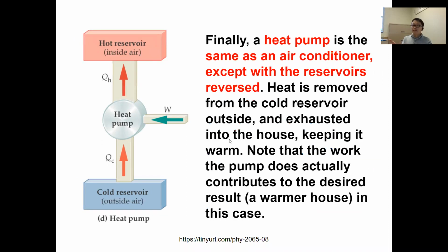And in the winter time, a heat pump works the same way as an AC or refrigerator. Now the air inside the house is the hot reservoir and the air outside is the cold reservoir. So it takes heat from outside and, with the work done added together, dumps it to the inside air.